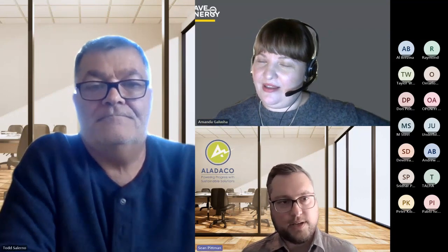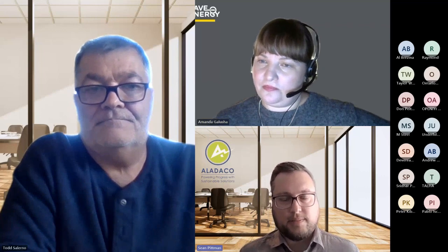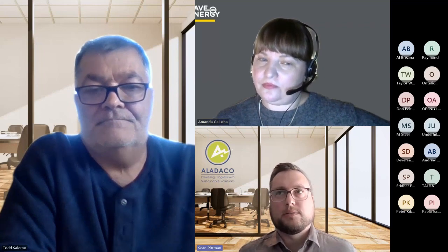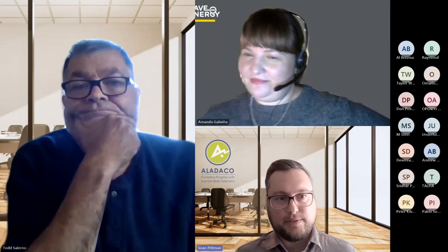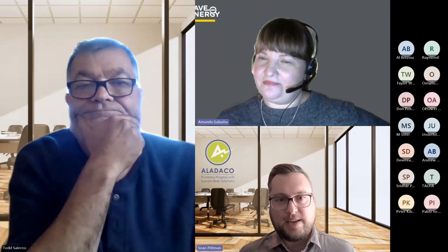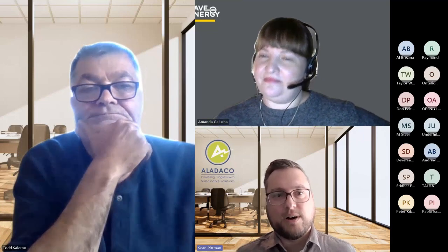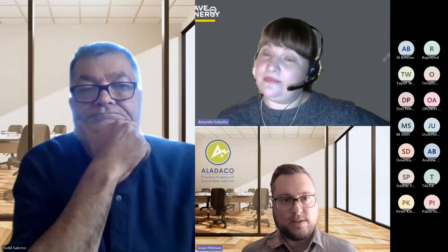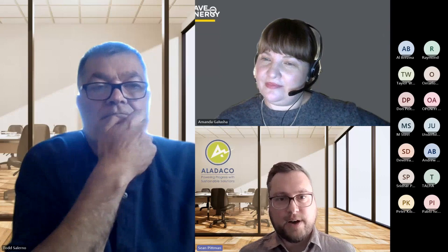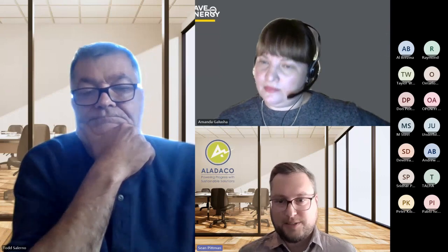I'll just echo that again. The more data that you have in the beginning, the better. You can never go back and get data that you missed out on getting the first time. So get as much as you can. Data's cheap these days. If you have the meters, record it. If you're not logging, start logging now, because you never know when you're going to need it. And storing a CSV file of some information really doesn't take much space or cost these days.